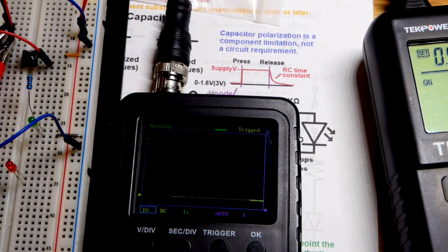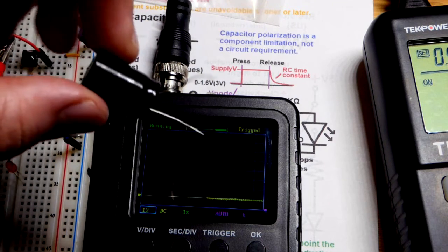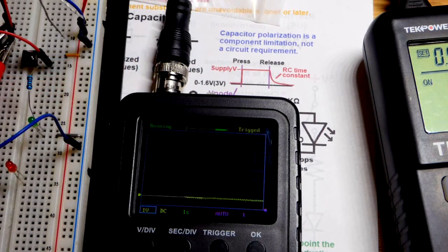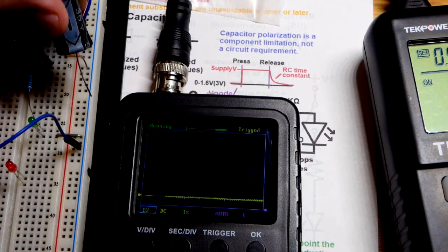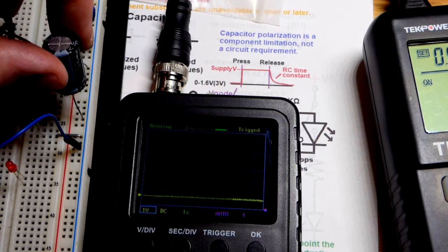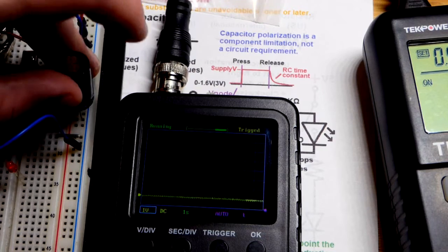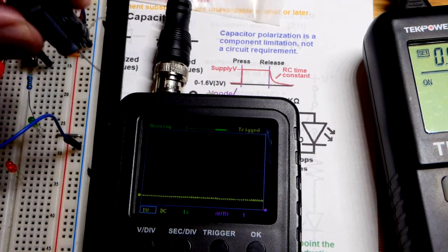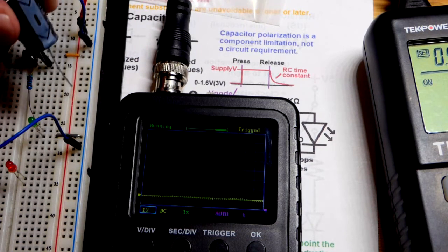So I'm going to pluck it out and take the 1000 microfarad capacitor. So this has 2000 times the capacitance. I'm going to make sure it's discharged. There may be a pop. There we go. We were dealing with 12 volts before, but in any case, no pop. We made sure it's discharged. It's good to always discharge them.